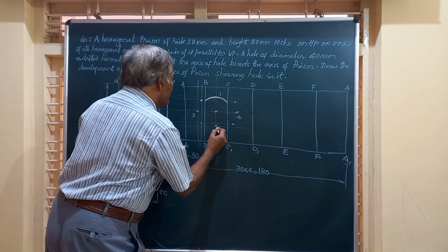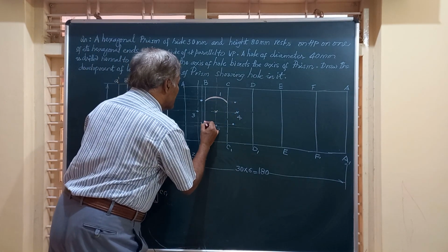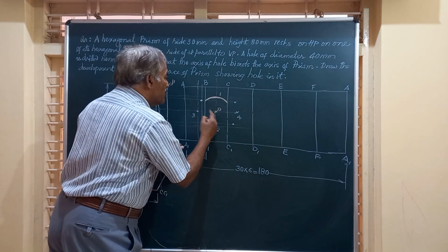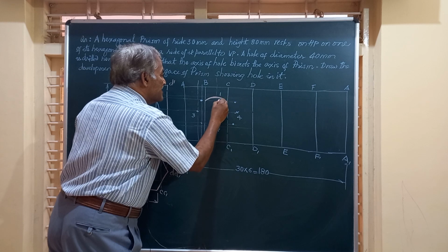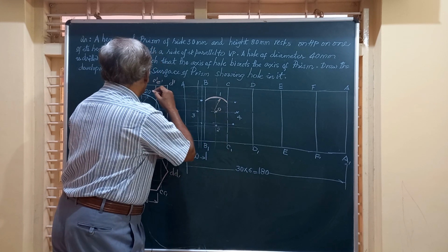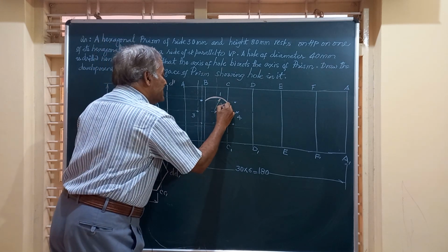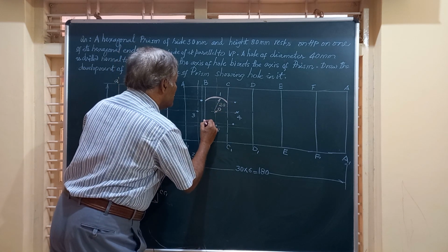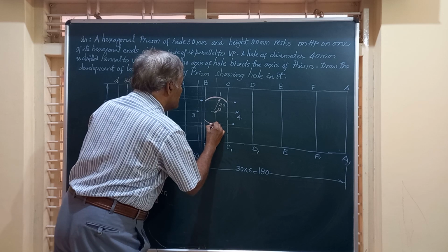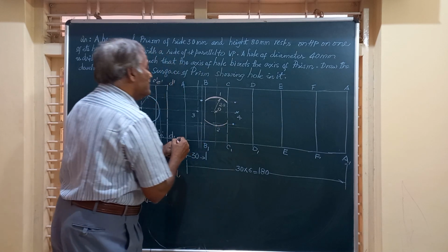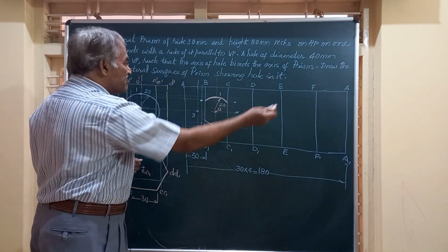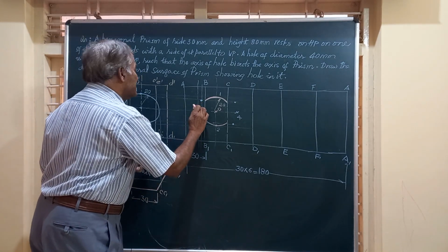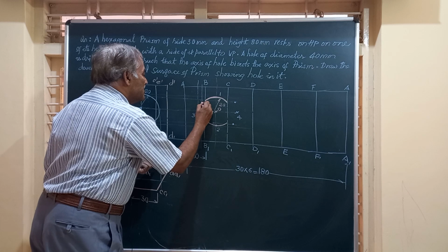Similarly, the bottom face also you can have an arc. That is with center O and radius equal to this radius, which is 20. You can draw one more curve here. Friends, we are going to have it symmetrically on the other end also. Friends, the remaining points, whatever you have got there, are to be joined by a smooth curve.